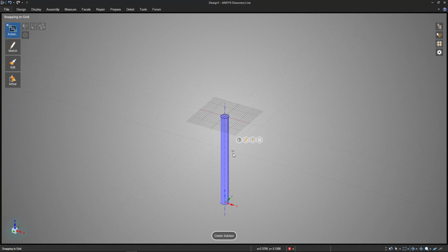Whenever you go to sketch after you've got something 3-dimensional, you usually have to define your sketch plane. That's the first click. So I've already got the very top of my circle here, which was selected when I went for that option, being defined as the thing that I'm sketching on. You can always change that using some of the navigation buttons here.